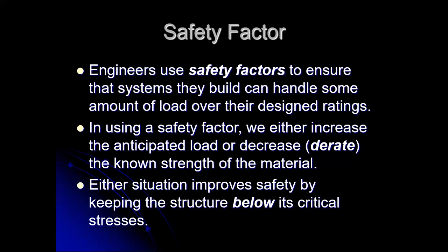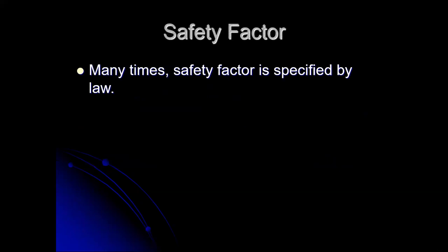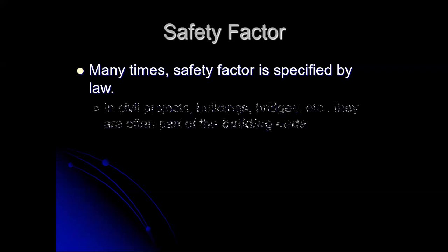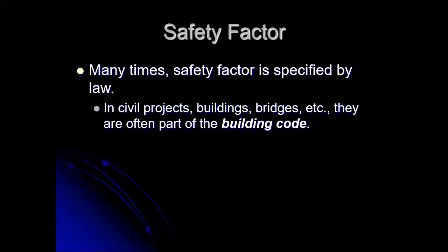Now, in either case, we keep the structural stresses below critical values, and that improves safety, gives us margin. A lot of times in public works, safety factor is specified by law. So when you go out to build a bridge, if a company bids on building a bridge, there is a particular safety factor that can be looked up in the code. So building codes, bridges, buildings, etc., they're part of the appropriate building code for whatever is being built.